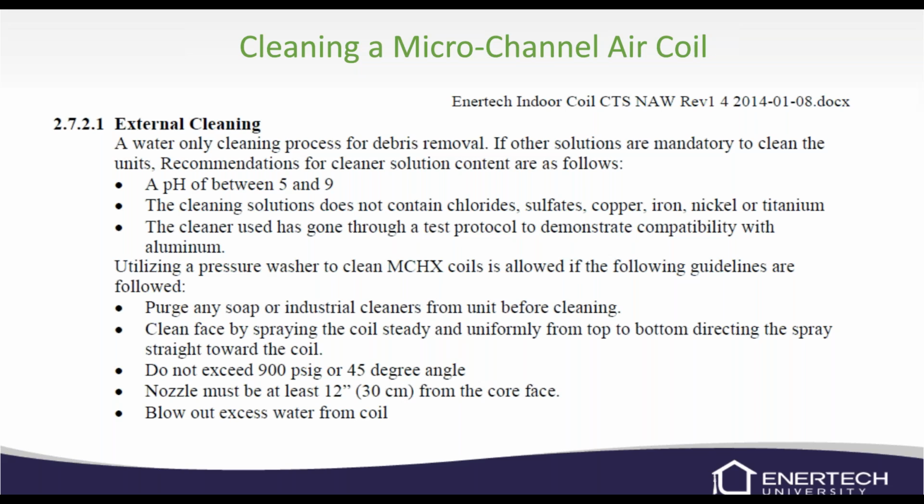The best way to clean a microchannel air coil is to keep it clean. It's hard to really clean them with water in place because they're usually inside the home. So the best way is just to keep it clean, and don't use them during construction. Drywall dust gets stuck in these passageways and it's really hard to get it out. If it did get some drywall dust, or you've got an old cat lady or something, you may want to use a shop vac and see if you can pull it off with a vacuum.